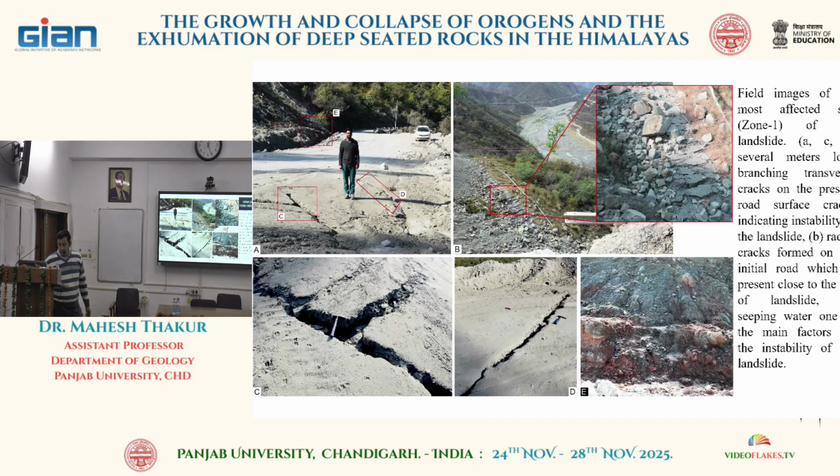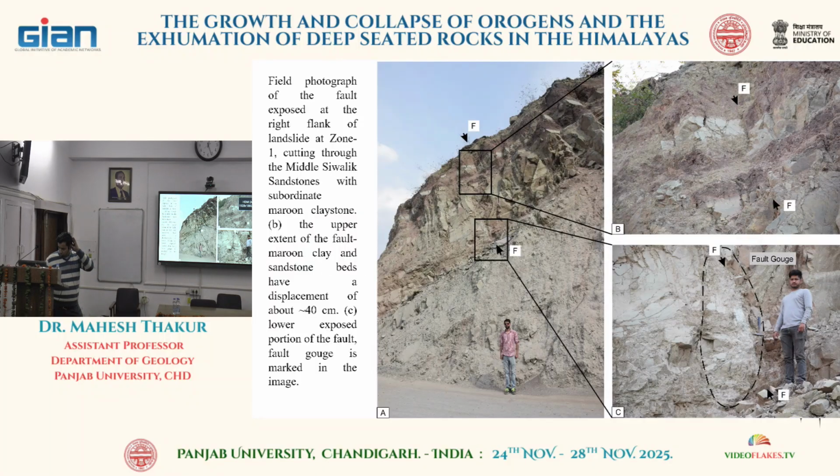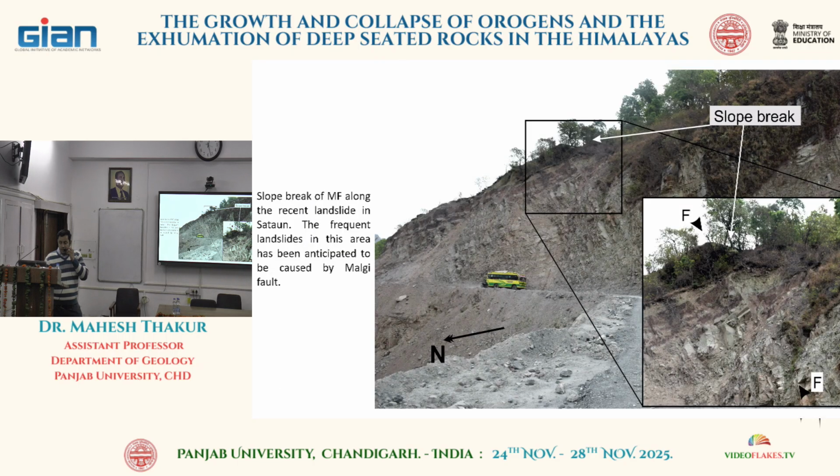So one thing I want to say is that when we collect this joint data in the field, you can see this rock is dipping, and there are a lot of joints, and those joints are used to do kinematic analysis in order to understand what type of rock failure can happen. We classify planar failure, wedge failure, toppling failure. And then some of this geotechnical data you can put into software and try to see the slope configuration, whether it can fail or not. That kind of thing we can do when we go in the field.